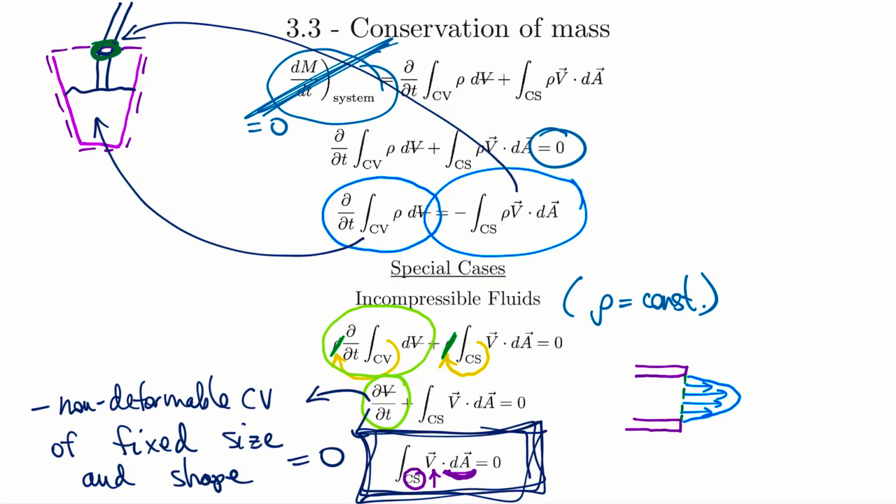So these right here are the velocity values. In green, that's our area, that's our control surface, the area that we're integrating over. So I only need to integrate when this velocity changes over this area, which, like we've seen, is going to be a lot of cases. But I could skip the integration if I had a way of writing a uniform velocity or an average velocity that took into account this integration already. So let's look at that.